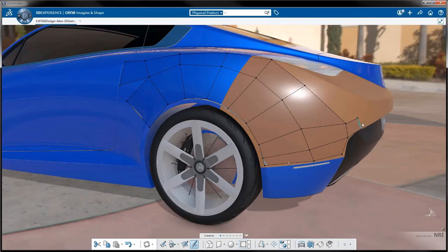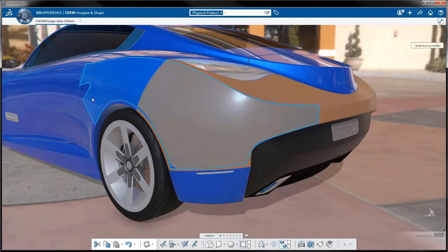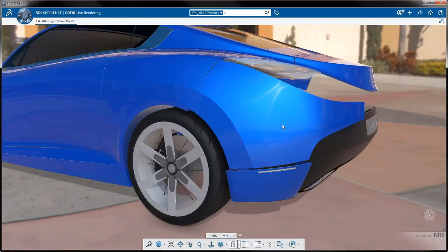And it's view dependent. So whatever view you're in, that is the direction that it gets suctioned. And these extrusions detect the closest edge and snap to assist the user. So moving those vertices around is easy. And the edge treatments can also be made. So you can see that along the wheel lip.